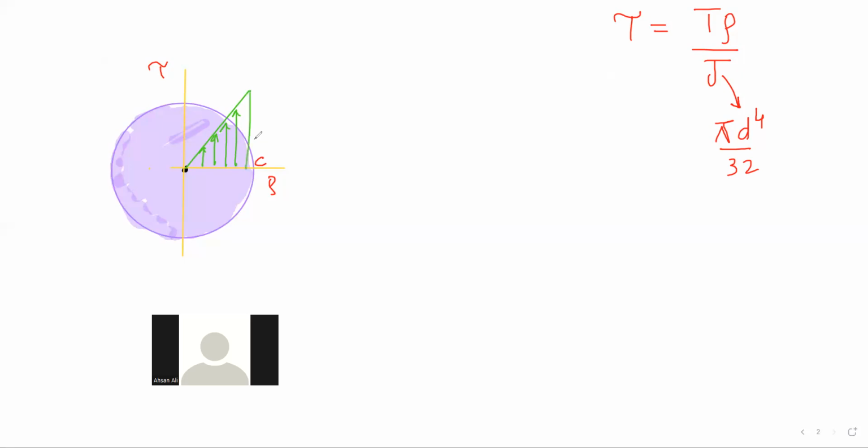My whole point of first telling you the concept is, if I had started with a mathematical derivation, you would be like, oh, what is happening? But now when I do the derivation, probably next class, at least all of you will have an idea what is happening. Agreed? Disagreed? For this graph, we said that the shear stress will be linear, proportional to the radius. But this is a pure twisting problem. Every time you see the formula, start to twist the pens like this.